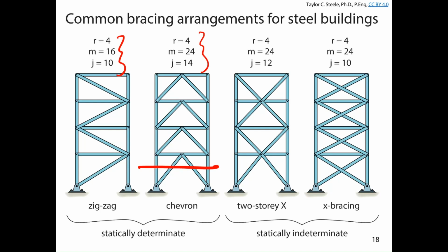I've got 3, right, equations of equilibrium. Can I figure out what those 4 member forces are with that section cut? Yes, no, maybe so. I can't, right? I've got 4 unknowns and 3 equations. That means I can get all of them in terms of another force, but I need something else. Usually that would be compatibility or some kind of flexibility considerations.